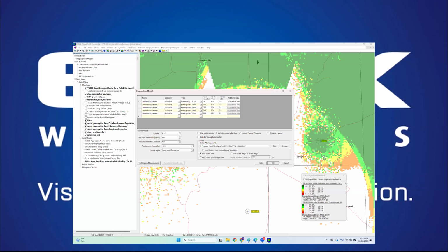Maybe I have these set at 50% of time and location, and I go out and do some field testing, test against measurements and adjust my clutter losses, or I just decide to apply some margin. As long as I can get my propagation model, if I just run received power, to largely line up with what I measure in the field,